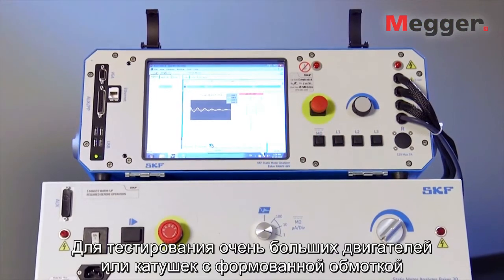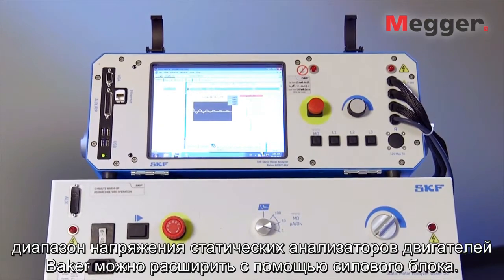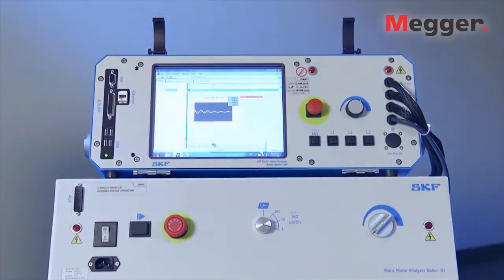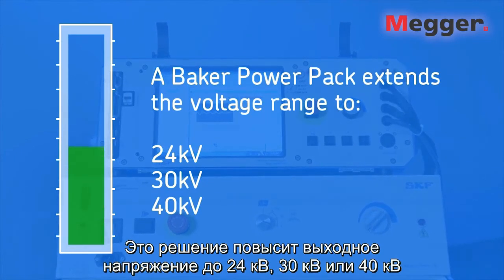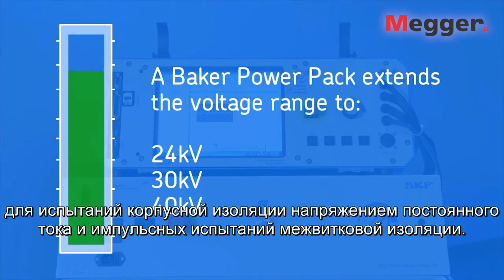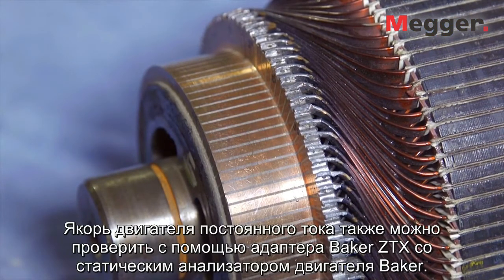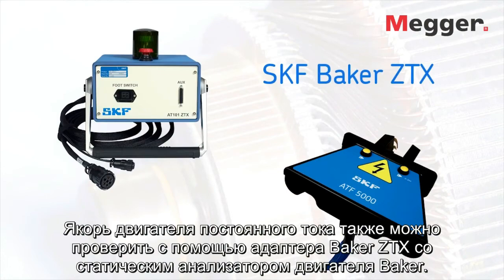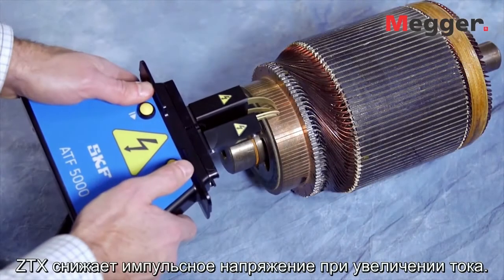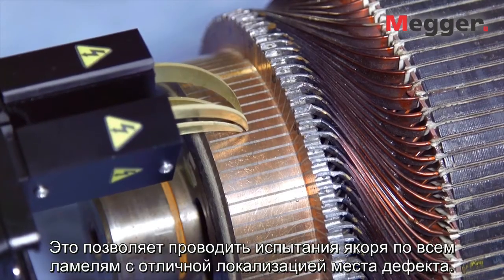For testing of very large motors or form-wound coils, the voltage range of static motor analyzers can be extended using a power pack. These solutions boost the output voltage to 24 kV, 30 kV, or 40 kV for the ground wall insulation DC tests and the turn-to-turn insulation surge test. DC motor armatures can also be tested using Baker's ZTX adapter with a static motor analyzer. The ZTX lowers the surge voltage while increasing the current. This allows bar-to-bar testing of the armature with excellent fault location.